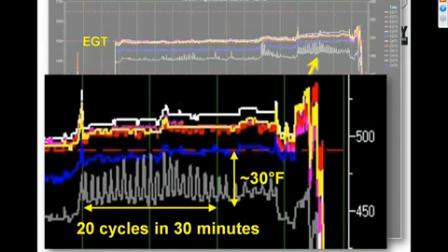when the engine is running at a typical cruise RPM, say 2400 RPM, the valve rotates just slightly slower than 1 cycle per minute. And as the valve rotates, when the worst spot on the valve matches up with the worst spot on the seat, we get the maximum amount of exhaust leakage, and you get a little rise in EGT. And when the valve rotates so that the worst spots are not aligned, then the leakage is a little bit less, and the EGT comes down, and we get a perfectly rhythmic oscillation, which is the hallmark of a failing exhaust valve.